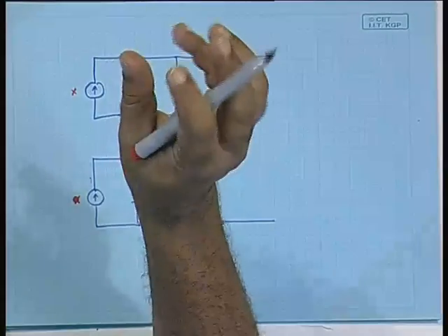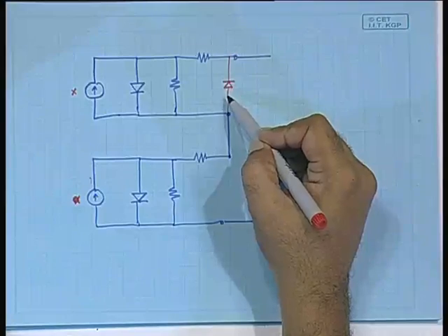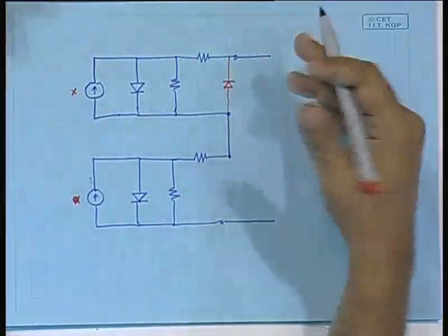So, there are sometimes hot spots generated, a particular cell heats up, the one that receives no solar energy, which is shaded, heats up more, and sometimes that results in damage of the cell. This can avoid that damage, and moreover, whenever there is a shading in a particular cell, if this diode is provided, then it can allow the path.